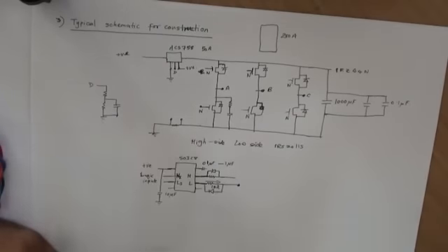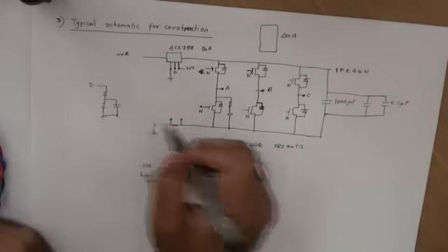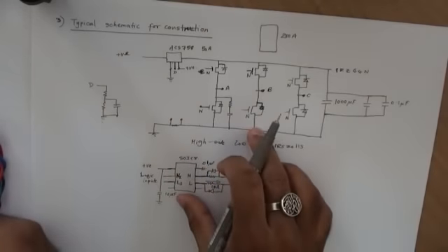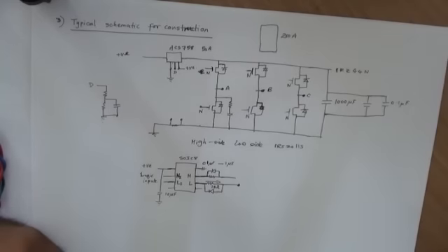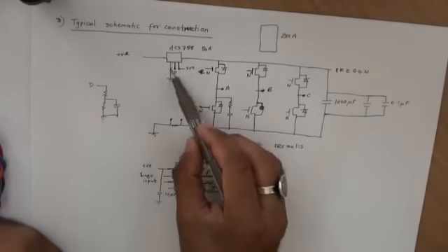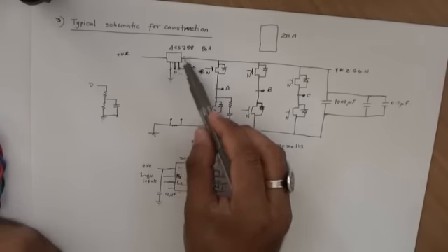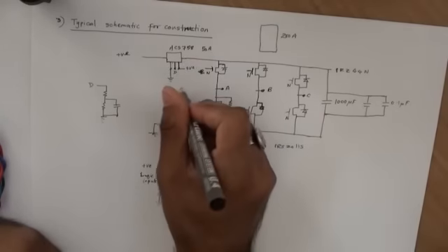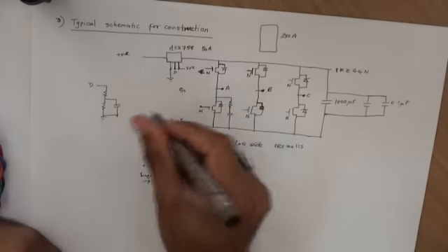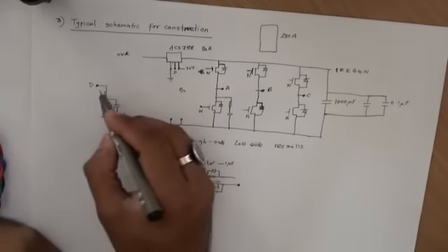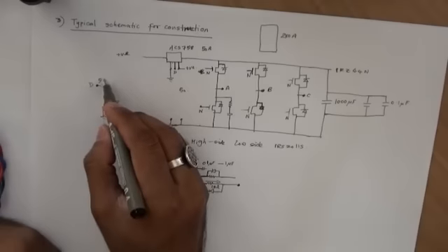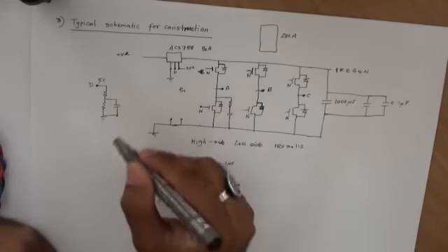They're very useful. Now the reason you want to voltage divide them is because depending on the microcontroller you're using, your ADC input to the microcontroller may be low. So for instance, if you're supplying this ACS758 with 5 volt, then you could potentially have up to 5 volt on your output D if you go onto the full scale.